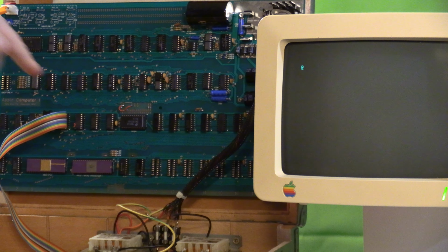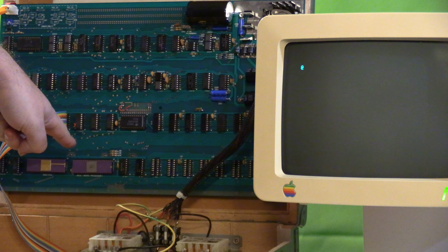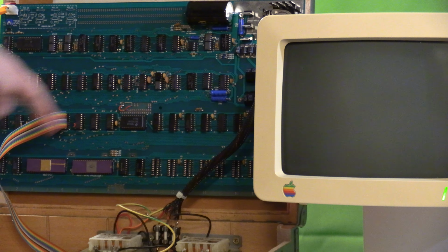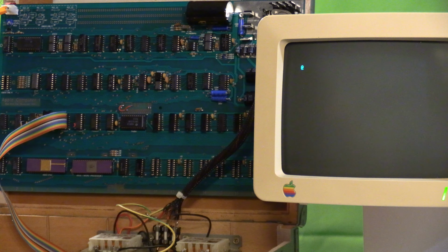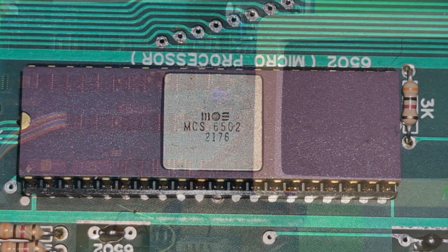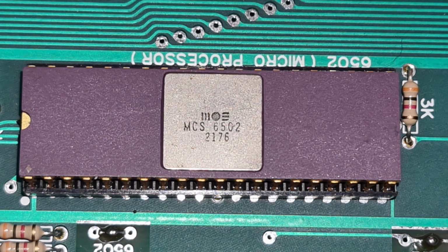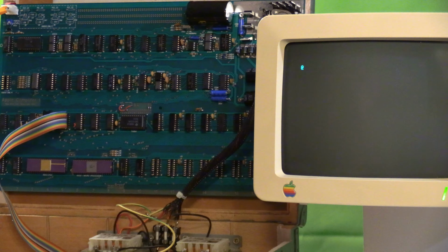Welcome! In this video I will talk about the so-called ROR bug of early 6502 CPUs that were produced before June 1976. It turns out that these CPUs don't have a buggy implementation of the ROR instruction, but are missing the instruction altogether on the silicon die. This can be proven by a missing circuit that could transfer the carry flag to bit 7 of the accumulator. Without this circuit, ROR is impossible to implement.